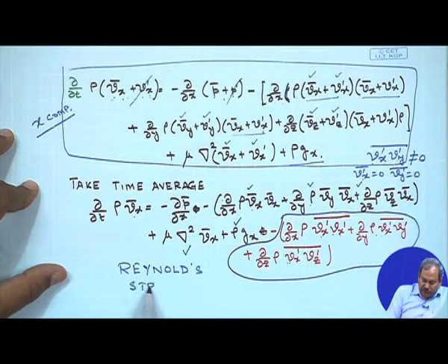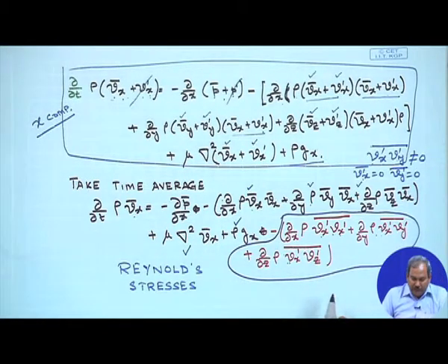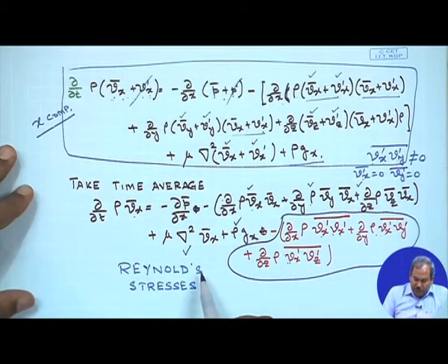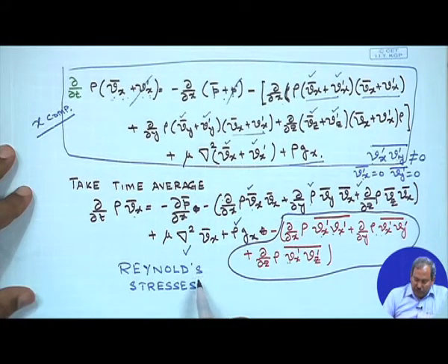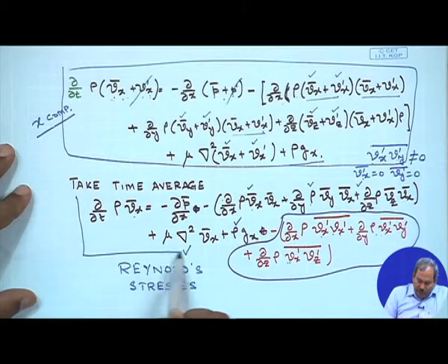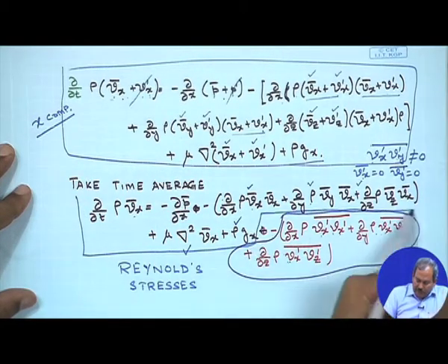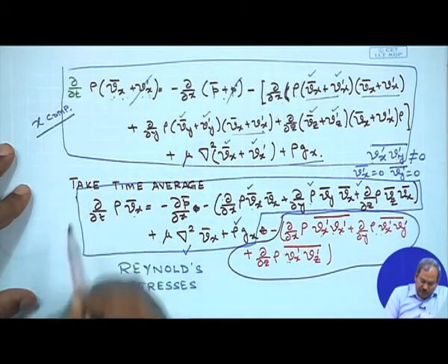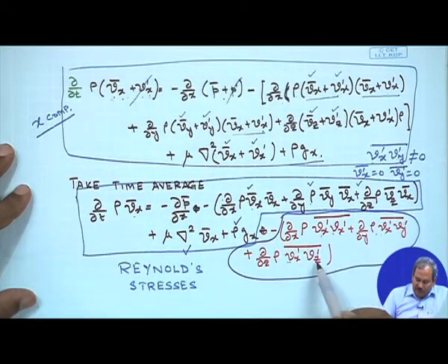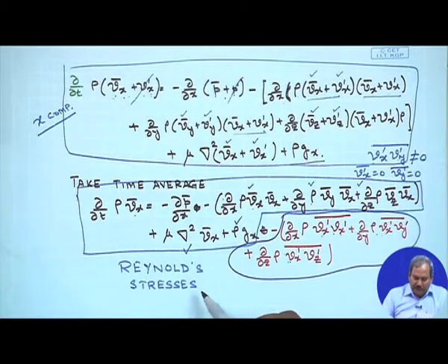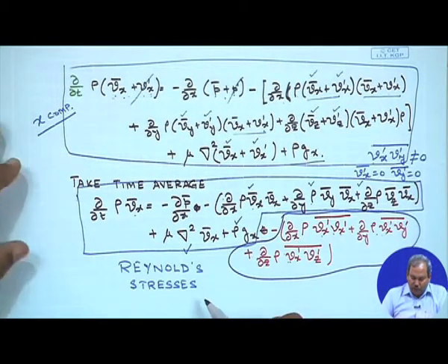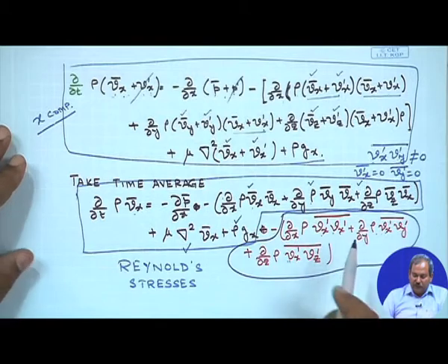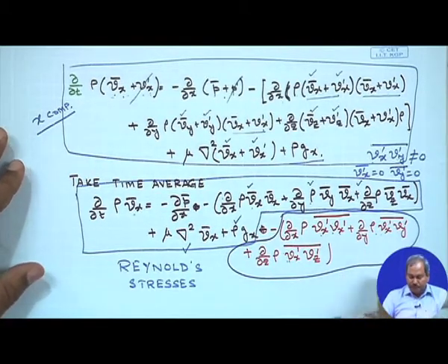And the Reynolds stresses are responsible for the additional, turbulent transport of momentum over and above that one would expect in the case of laminar flow. So up to this part, this is the laminar flow equation, and the three terms known as the Reynolds stresses essentially refer to the additional transport terms.